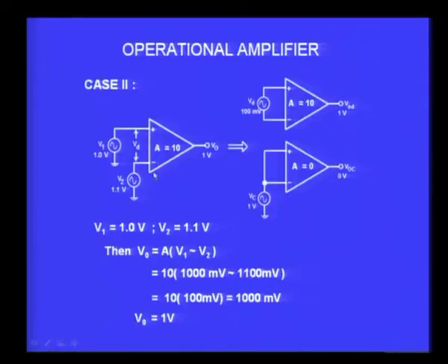volt, that means this type of amplifier is not at all worried about the signal which is common to both the inputs, whether it is 0 and 100 millivolt, or whether it is 1 volt and 1.1, or it is 5 volts and 5.1, whatever, the output voltage is 1 volt, which is nothing but the difference in voltage multiplied by the gain. 100 multiplied by 10 is 1 volt, and that is constant irrespective of what is the common voltage that I have at the two inputs.